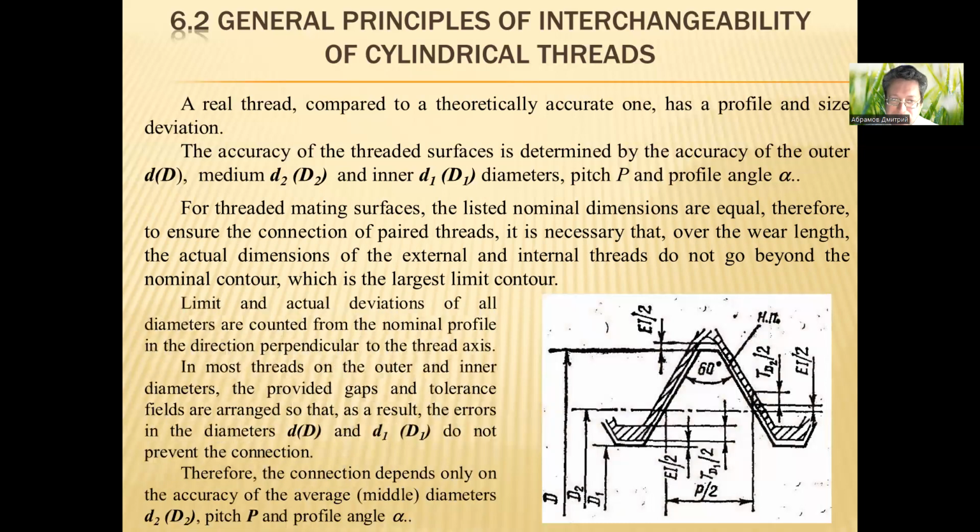Limit and actual deviations of all diameters are counted from the nominal profile in the direction perpendicular to the thread axis.